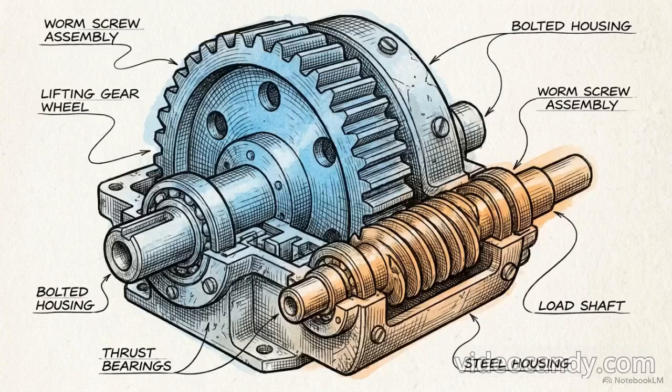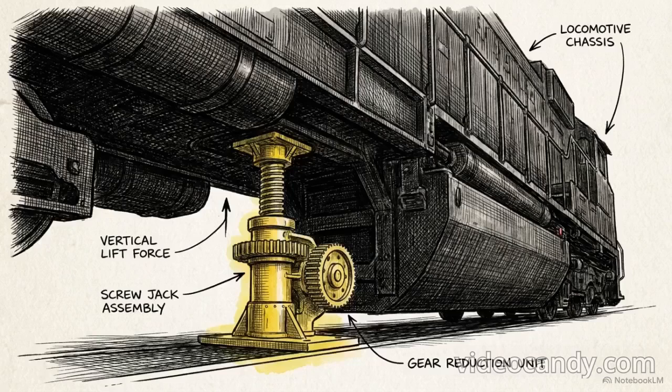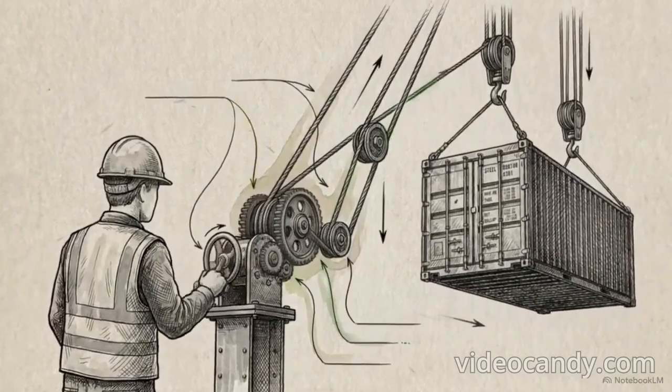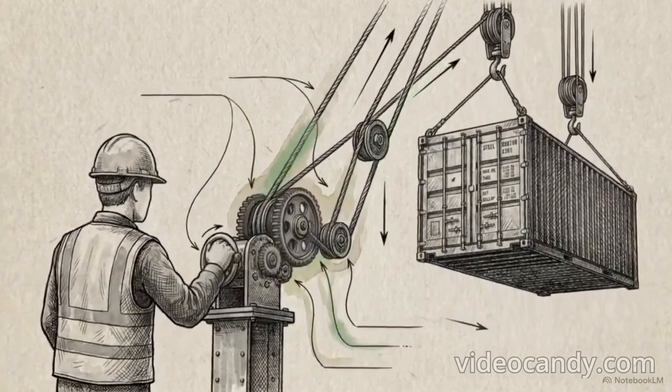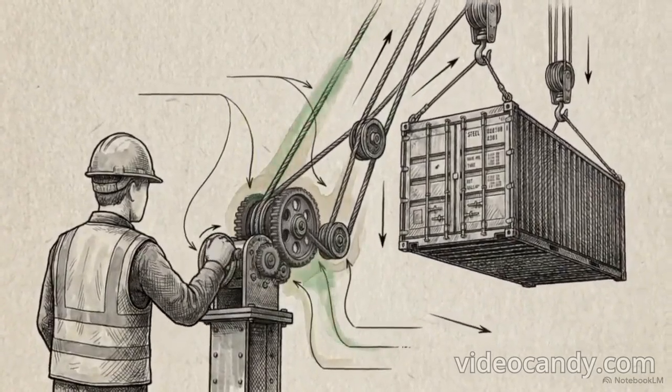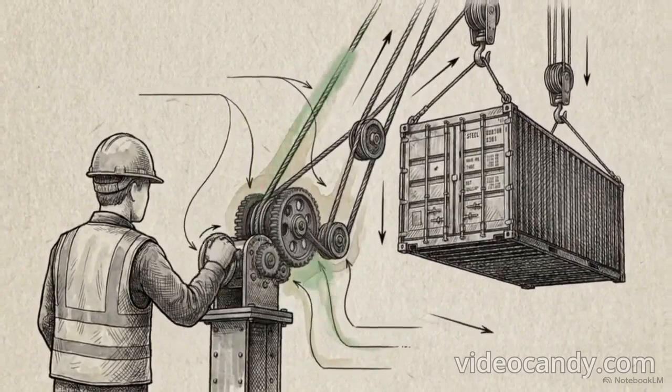These formulas govern simple levers and single pulleys, but modern engineering rarely relies on a single simple machine. To lift heavier loads, engineers design compound machines. This illustration shows how we layer multiple simple machines together to multiply the velocity ratio of the entire system. These configurations are standard in manufacturing, from differential wheel and axles to heavy-duty geared screw jacks. By mastering the mathematical ratios of distance and force, mechatronics engineers chain these simple mechanisms together, scaling fractional human effort into industrial power.